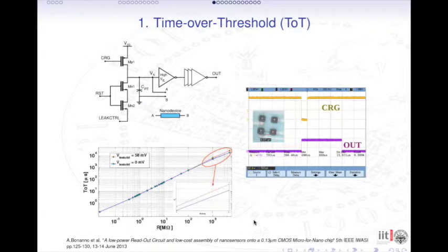This is just the first readout circuit that has been designed. It is only a proof of concept based on a relaxation oscillator. The conversion curve is linear. This transistor, MN2 transistor, is placed to exploit the stacking effect and to reduce the leakage in your circuit when you measure high resistance in the range of giga ohm.